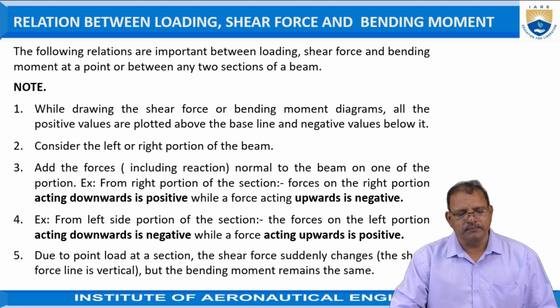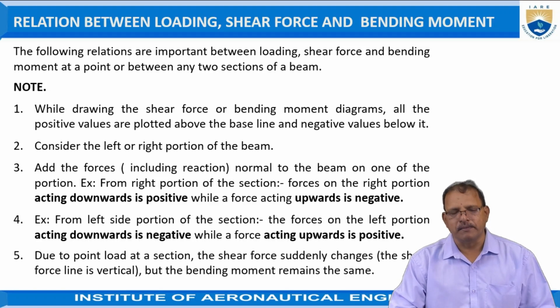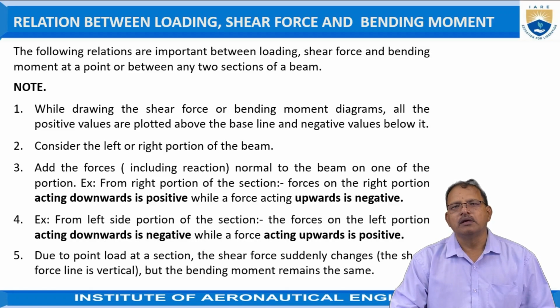The following relations are important between the loading, shear force and bending moment at a point or between two sections of the beam. While drawing the shear force and bending moment diagrams, all the positive values are plotted above the baseline and negative values below it.